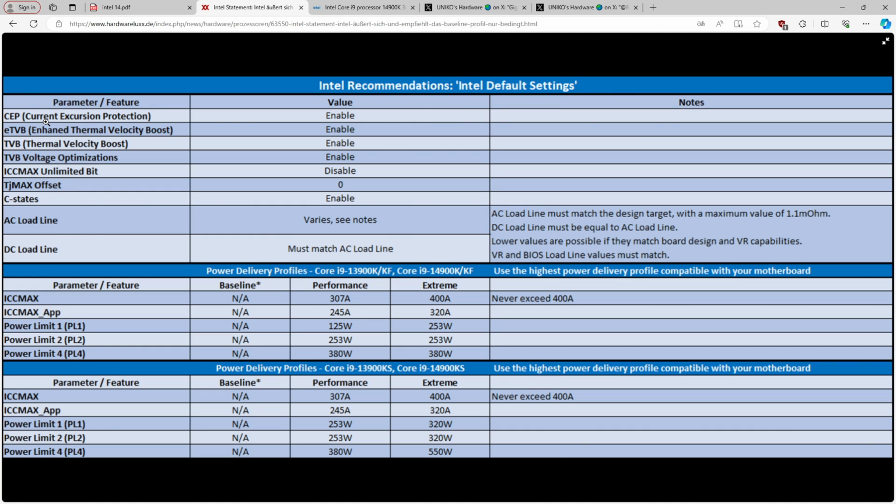Well, no, it's always going to end up at 1.2 volts, because if you set the power limit, it's going to do the same thing. Your cooling system basically acts like a power limit. If your cooling system can dissipate 300 watts, the CPU will output 300 watts, right? Frequency affects power consumption, but not as much as voltage. So if you're at 5 gigahertz and 1.2 volts, your power consumption is basically the same as if you're at 5.2 gigahertz and 1.2 volts.